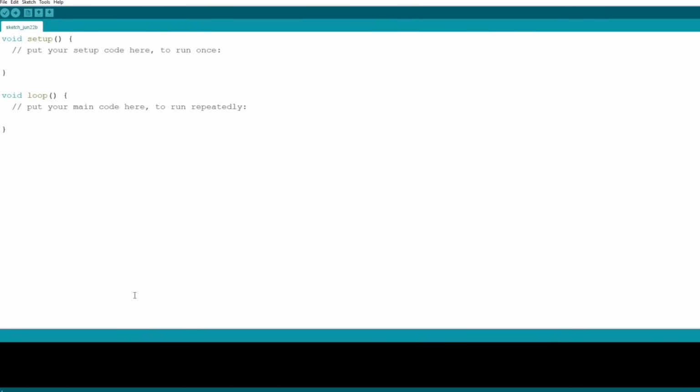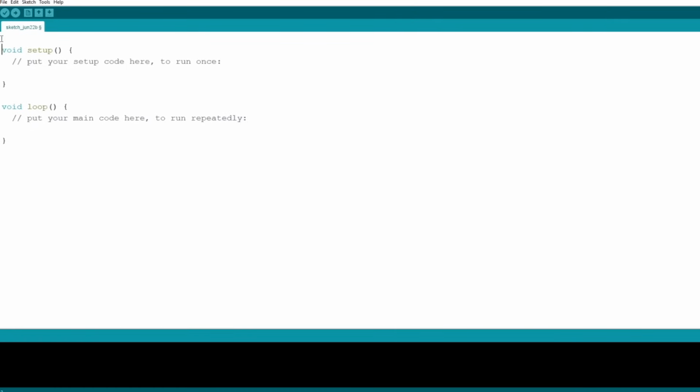And also then we need to add a new library to our source code for servo motor control. The name of this library is servo.h, so let's include this now. As you know, if you want to add any library to our Arduino code, what we have to do now is to include our library. So for this operation, first let's use a hashtag here and let's write include, and also let's use less and larger sign, and let's move inside of our less and larger sign and let's include our servo.h library, and we are done.